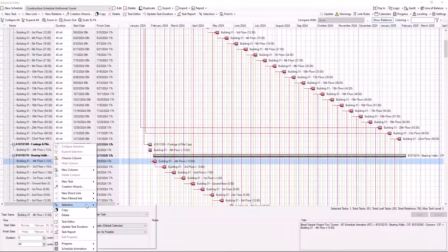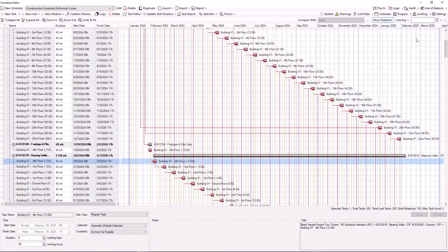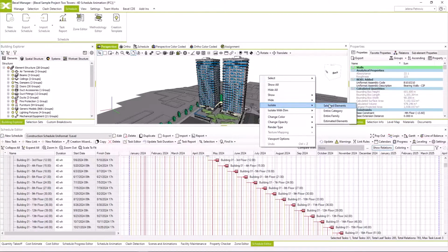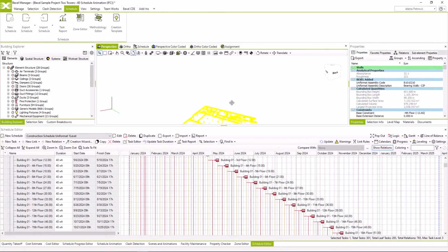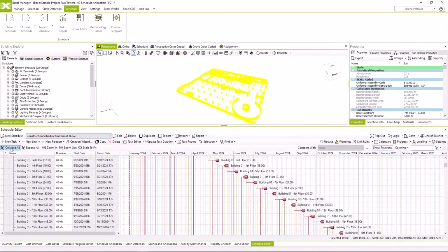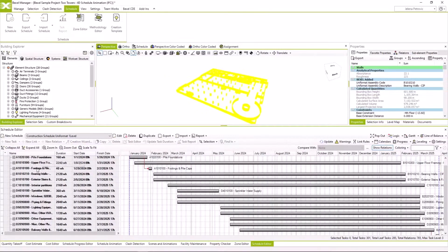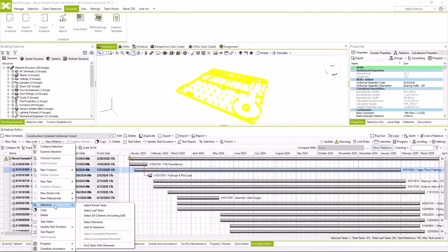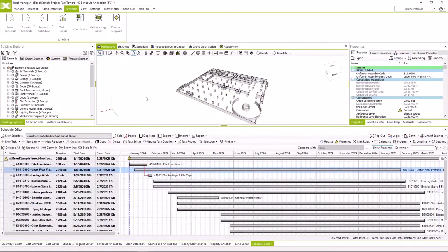As our BIM model elements are automatically connected with the created schedule, we can simply select Schedule Task and navigate our model to certain element position which are related to previously selected task. This way, we can easily overview which BIM model elements are, let me say, in automated way linked to the created schedule. Of course, I can activate color-coded view and see elements colored in different colors based on Uniformat classification code.